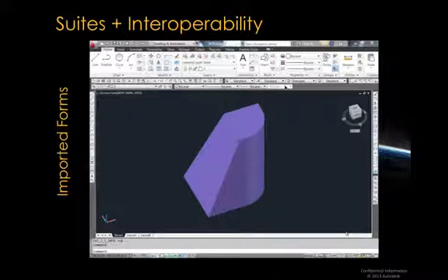These can then be offset to modify the resulting solid. That means that you can now in Revit 2014 use one single solid to define a whole parametric family of parts by importing the shape that you require and then modifying the offset of various planar surfaces on that shape to generate numerous different similar types.